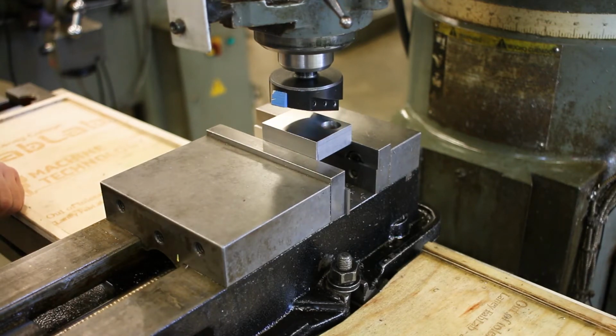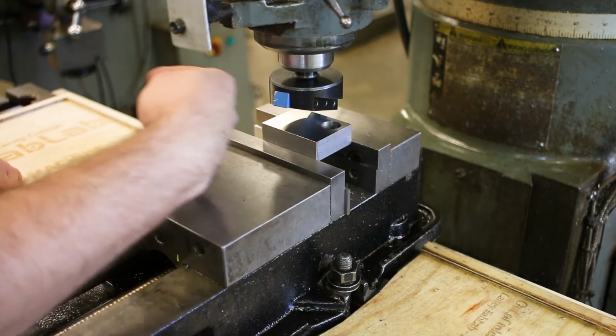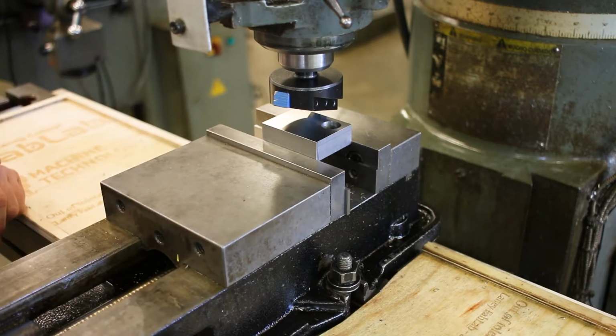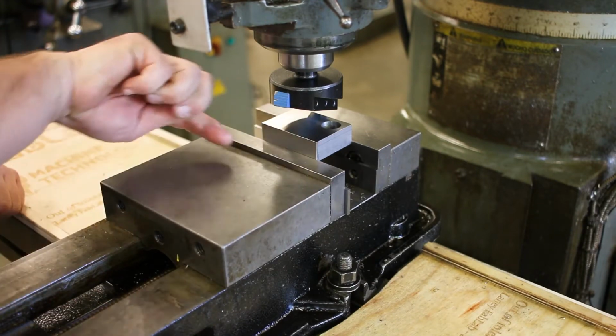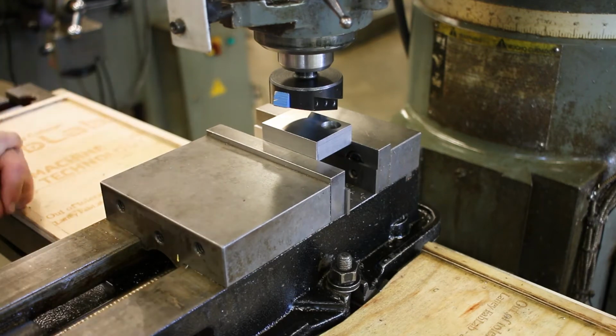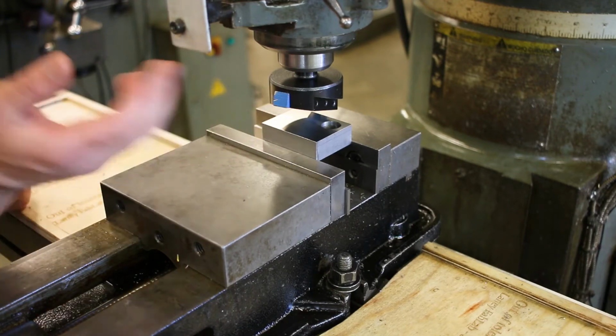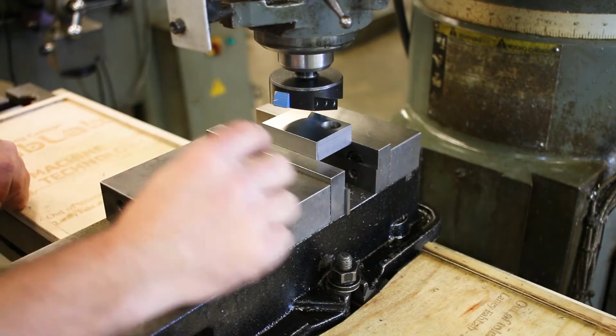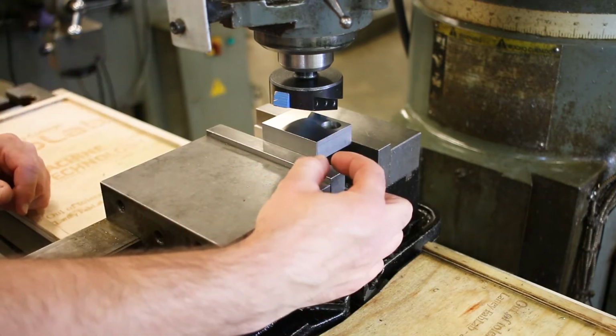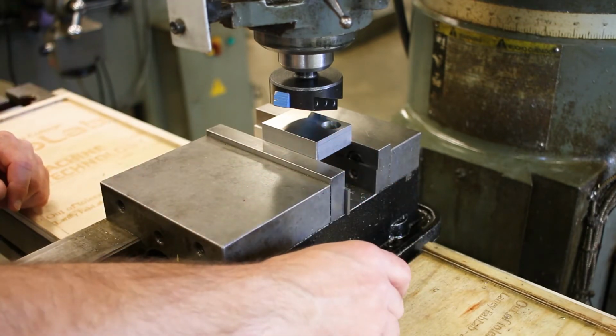With the fly cutters, we only usually cut on this forward stroke, I guess. We don't let it cut on the back, just because we get a slightly better surface that way. You know, really only taking a minimal cut here. 5 thousandths was all it took, so that's all I'm going to give it. There's no need to take some minimum distance here, right? It's just to clean up the surface.